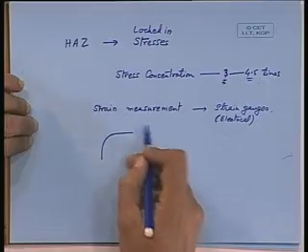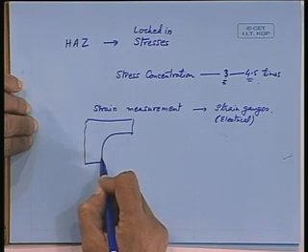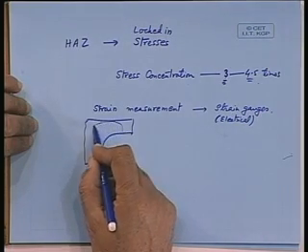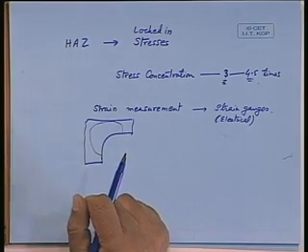Okay. Another one is a mechanical observation, just the qualitative arrangement, where you expect, say for example, when we are talking about this hatch part, and in this region you try to put some sort of a paint material, a brittle coating.